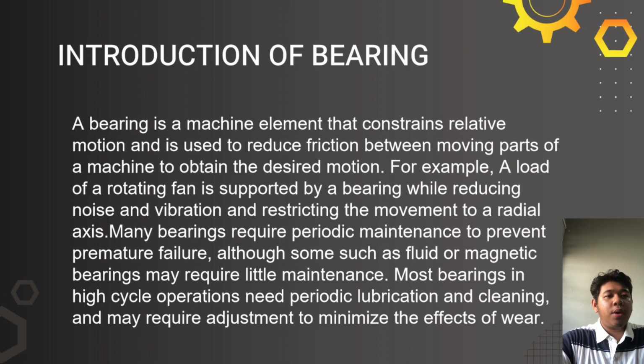Many bearings require periodic maintenance to prevent premature failure, although some, such as fluid or magnetic bearings, may require little maintenance. Most bearings in high cycle operation need periodic lubrication and cleaning and may require adjustment to minimize the effect of wear.